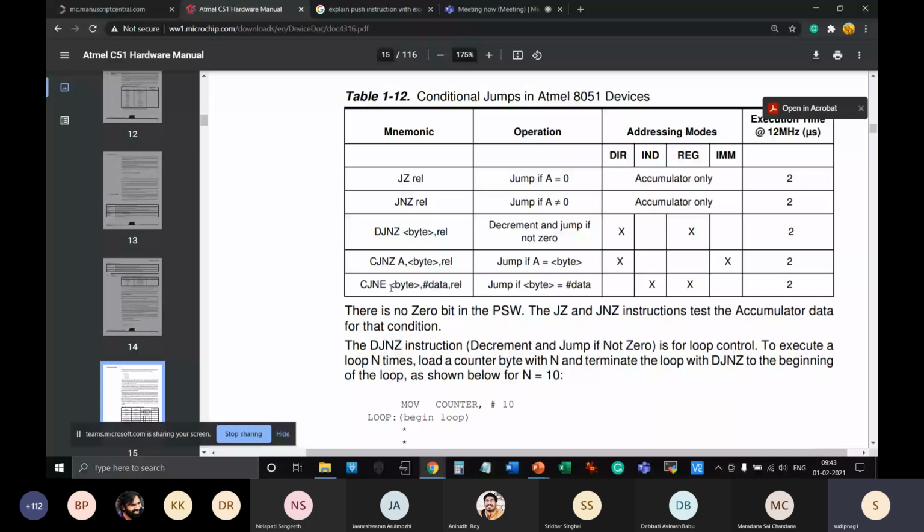But instead, the designers of the 8051 might have thought that they will have multiple opcodes for this part. So there is no single opcode for this mnemonic. The mnemonic CJNE with any byte has multiple opcodes. If it is A in place of byte, there is one opcode, for B another opcode, and so on. Only a handful of registers can fit over here. So that's why there are, I think, a few opcodes, around 10 or 12 possibilities.